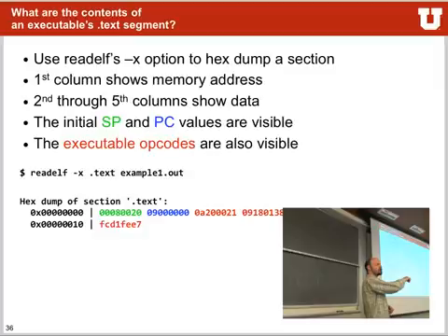It tells us that it's a thumb instruction because it's a 9 and not an 8, but this is the reset vector jump address, right? It's the start of where we start off at memory address 8. And that's here. And now if you want to go into details, you could start decoding this using the ARM manual and actually figure out what all the different opcodes are and what they represent as assembly instructions. And that's really what all this assembler does.